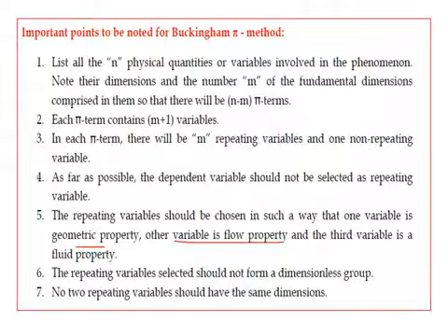The selected repeating variables should not by themselves form a dimensionless group, and no two repeating variables should have the same dimensions. That means you cannot select two flow properties or two length properties like that.